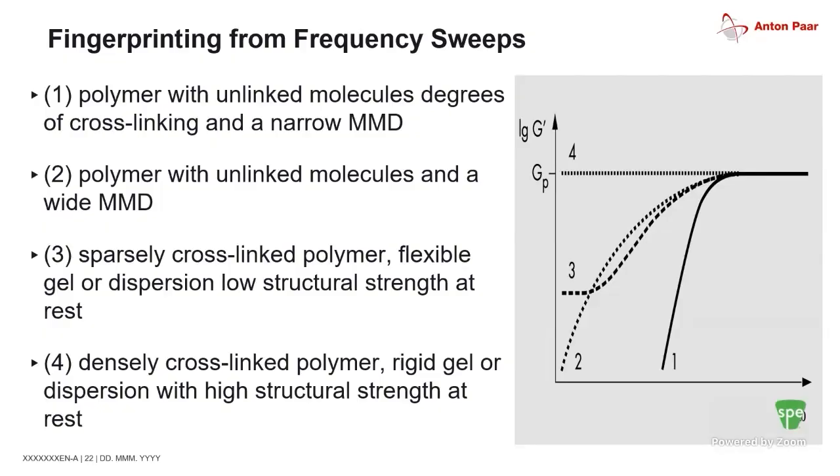So if I have a thermoplastic and we just look at the storage modulus, you will see it has a much broader decrease in the overall modulus, because again, the crossover point is going to be at a much higher frequency. So it's a narrower molecular weight distribution without really any cross-linking in that case, which is seen in image 1. Whereas if it's a much broader distribution, the curvature shifts to decreasing, say, to lower frequencies.